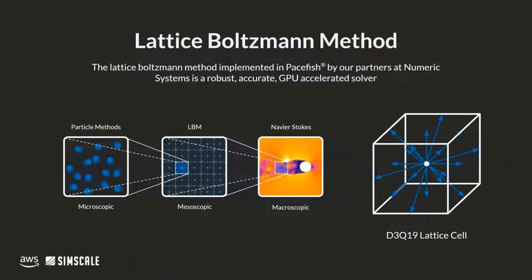Once the Drive AER geometries are uploaded onto the platform, the rest was all done in a web browser. Then after a brief 10-minute setup, including setting up the dimensions of the flow volume bounding box and inlet boundary conditions, the computational problem, defined by these setup parameters, was ready to be solved by the Lattice-Boltzmann method, a mesoscopic solver, as opposed to more traditional macroscopic solvers. From here, Pacefish's robust CAD-tolerant meshing algorithm takes in the geometry and forms the numerical domain, refining its accuracy down near the area of interest.